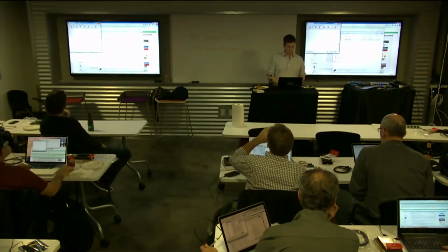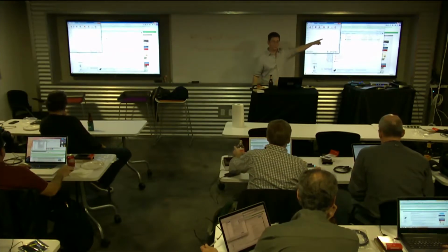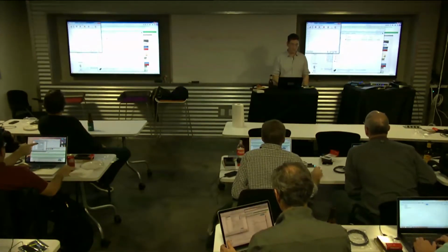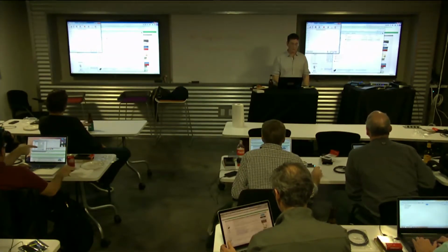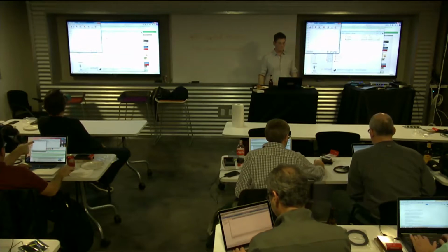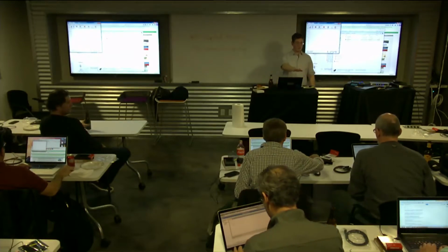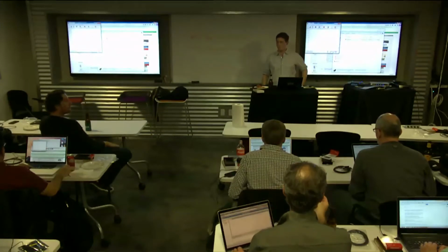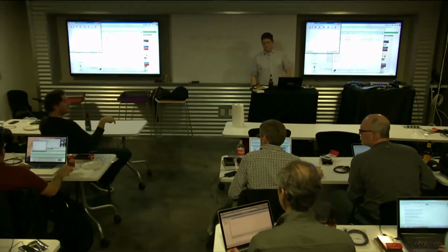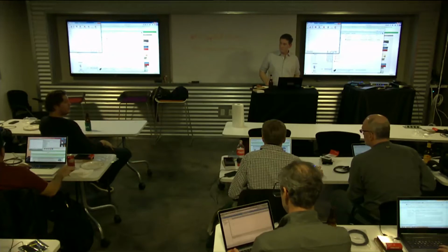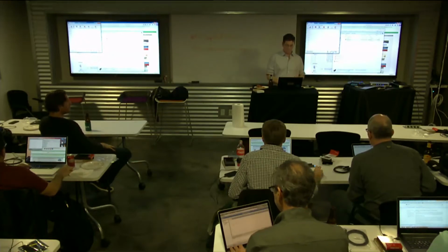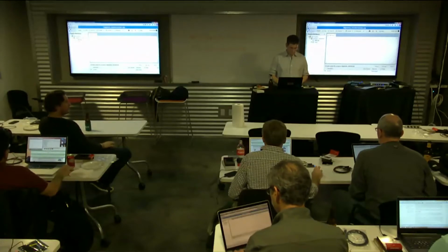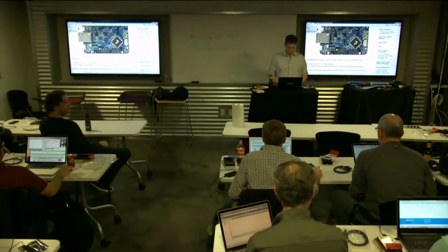Yeah. So there's my thing going off. What did you hit to make that go? This magical button right here called Connect. You can see it as COM45. You'll see it as something else, I promise. Especially if you're on Mac, it'll be different. You may have to go to the settings on Mac because there's probably already a few pieces of hardware on your computer. So if you go to the settings and look at the drop down, it's going to be something like USB modem, with a bunch of numbers at the end of it.